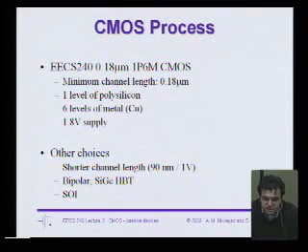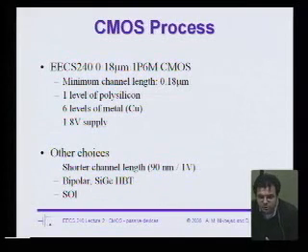And people call that system in a package, or multi-chip modules. So you would have one chip that would be your digital, another chip that's your analog, and you'd pack them together in one package very closely as if it's a single system, but now it's the system in the package. Okay. So if you talk to a lot of good analog designers, they would probably argue that 0.18 was the optimal point. After that, things just went bad, so to speak. Maybe even quarter micron.